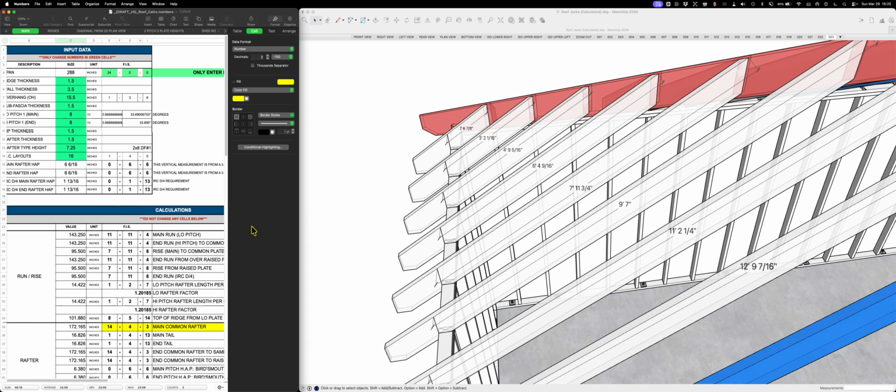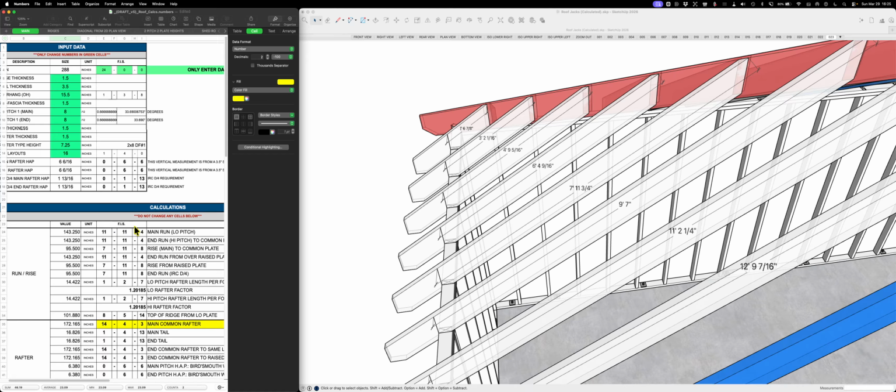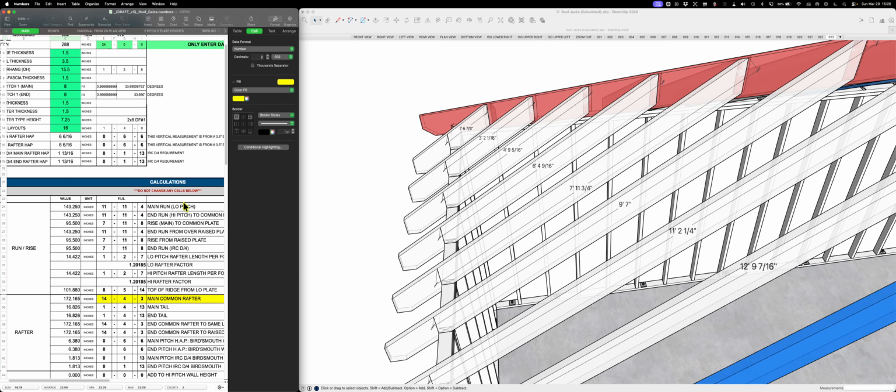So a 24-foot span minus 8.5 divided by 2 is 11 foot 11 and a quarter. And I used feet-inch-16ths ever since when I was in Tennessee, and the truss company guys would send out trusses, and they always use this. And at first I was like, what is the deal? You know? And then I realized I had to do it here on Excel because to make it do fractions, there's a lot of weird programming you have to understand. And so that was beyond me. And I was able to make this do feet-inch-16.